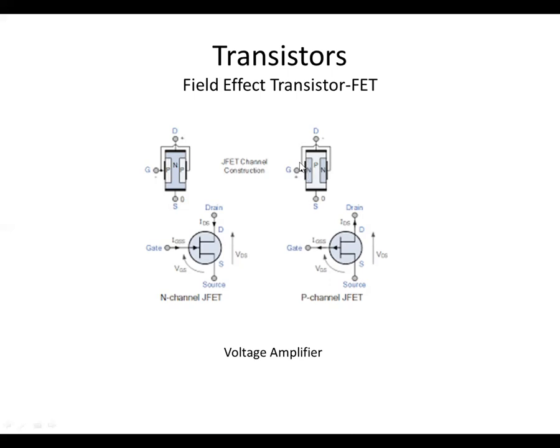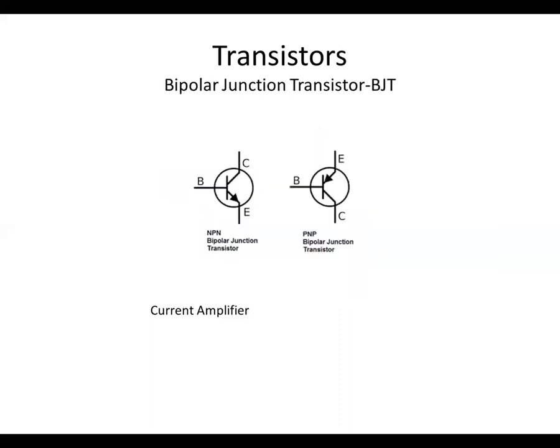As you apply a voltage to the N material, it restricts and becomes smaller. There's a field here that restricts the path for the current flow and changes the resistance. So it's called a valve transistor because it kind of acts as a valve. A valve being a triode vacuum tube. So it's very similar in function to a triode vacuum tube. Just remember, it's a voltage amplifier, and the BJT is a current amplifier.